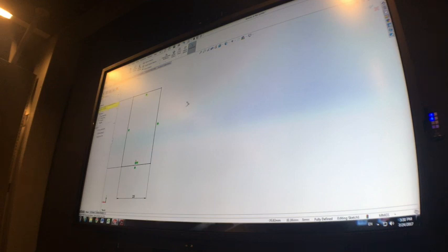The offset tool we looked at very quickly last week. So offset entities on your sketch toolbar, and included under that are a few different options. The basic way it works is you click on a line, and the yellow preview shows you where it will offset that line to. With none of those options selected, it's just going to create a new line out in space. Whatever dimension you had in there, and you can see if I move this first one, that second one's going to move with it, because it's offset, and you can see there the offset relation.